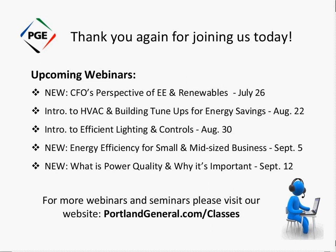That's a really good question. The energy experts that I mentioned that are on our staff here remind me that on the energy bill, there is a demand charge for a lot of the commercial and almost all the industrial customers. Usually it's less than 10% of your energy bill if you separated your demand charges from your energy charges. And they advise that if you focus on reducing the kWh, then the demand will go down with it.